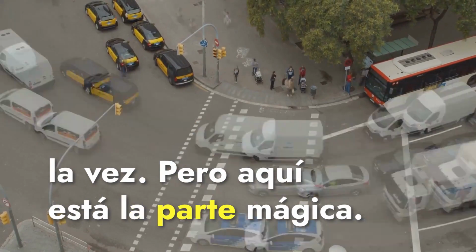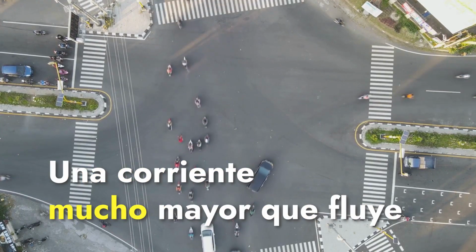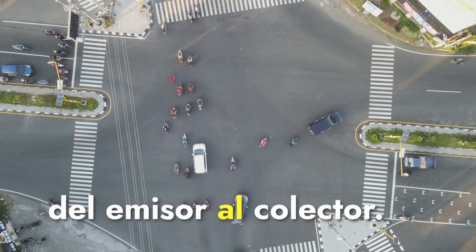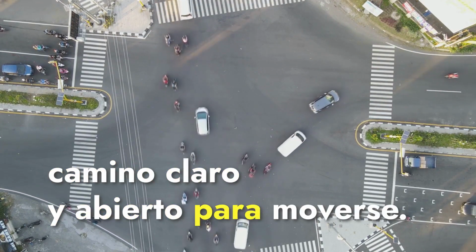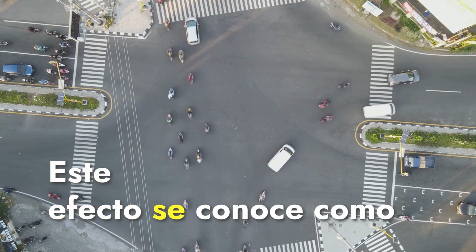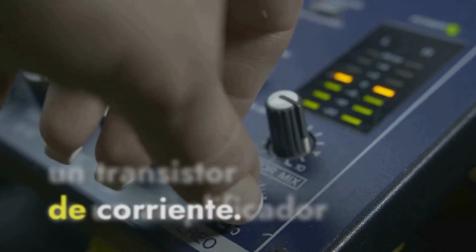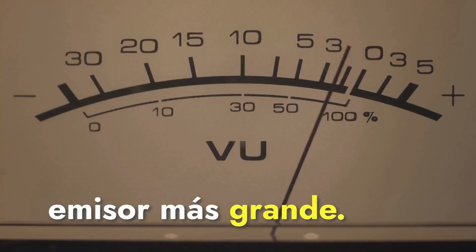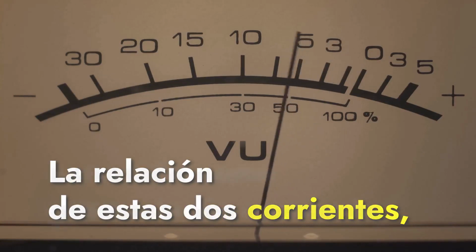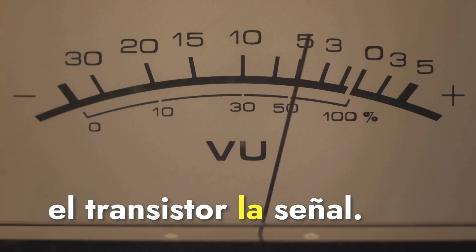But here's the magic part. This small current that squeezes through the base controls a much larger current that flows from the emitter to the collector. It's like the crowd of people now has a clear, wide-open path to move through. This effect is known as amplification. In a nutshell, a transistor is a current amplifier. The small base current controls the larger emitter-collector current. The ratio of these two currents, known as the current gain, determines how much the transistor amplifies the signal.